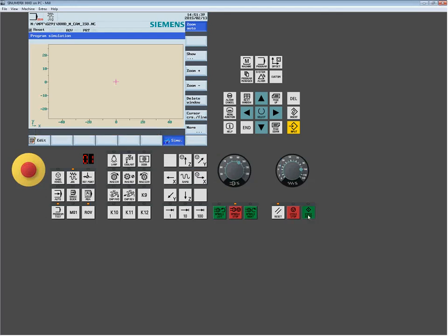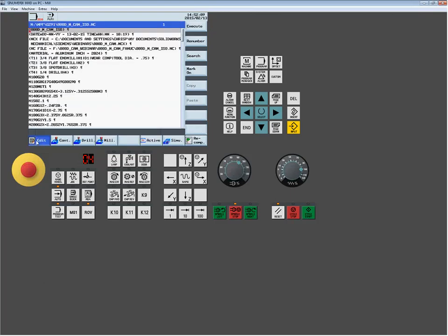Okay, so I come in, cycle start. Oh, put it into auto mode. And now, if we zoom in, now we see our fluid sweeping arc. So be careful with that. In ISO-based programs, when I'm putting on cutter comp and I've already compensated for the tool, I do need to set my tool radiuses at 0, or I'll get double compensation, just like we saw over in the other side.